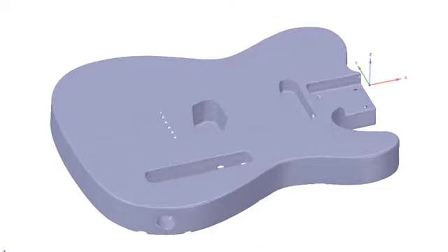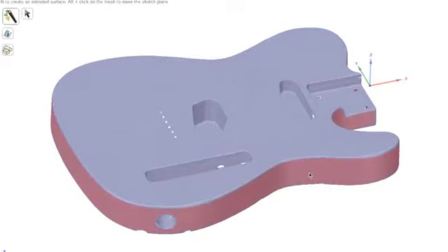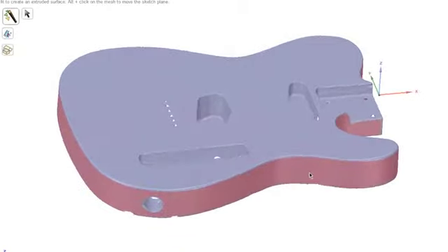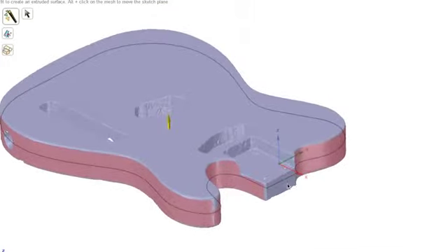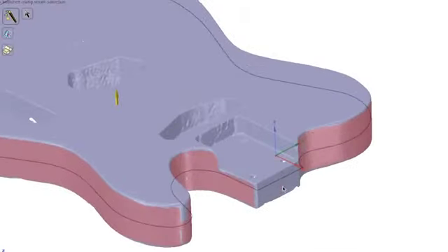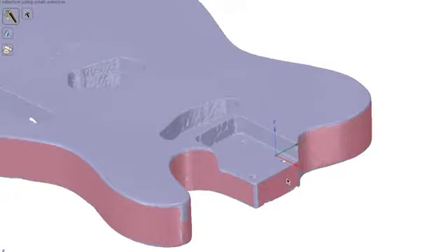So I'm going to use a fit extrusion command. And I'm going to click on the triangles on the outside of the part, and you can see that there's a selection there. It turns red. And just like Windows or Microsoft products, I can hold Shift and select more missing faces.